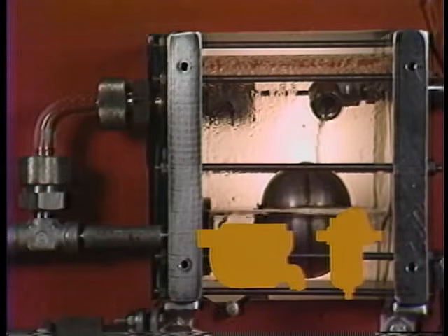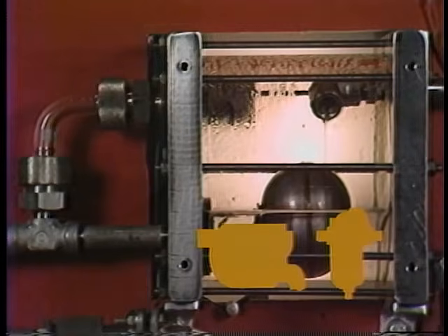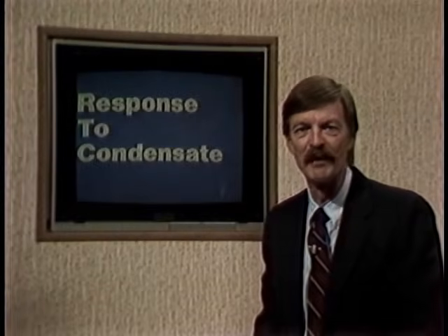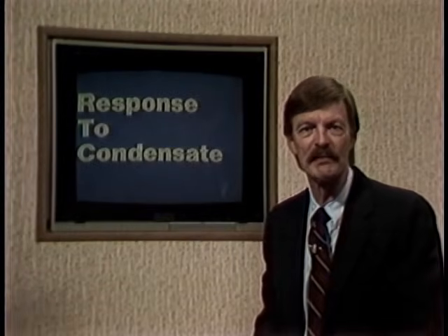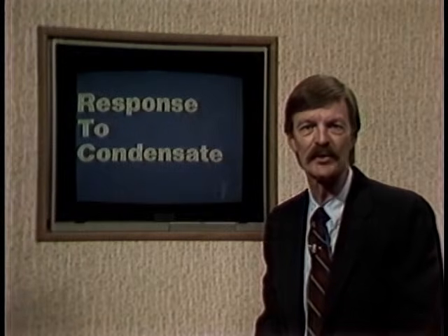F&T and DC traps pass live steam mixed with any air they vent. While this loss is greater than with other traps, it is generally considered acceptable in applications which require the venting of large air accumulations. Production rates, ambient temperature, and steam quality are just a few of the factors which vary the condensate load to the trap.